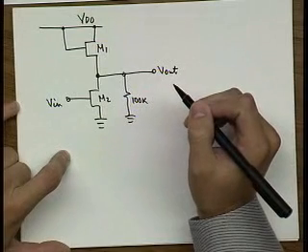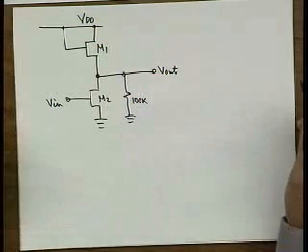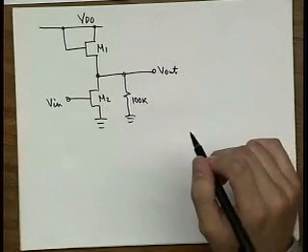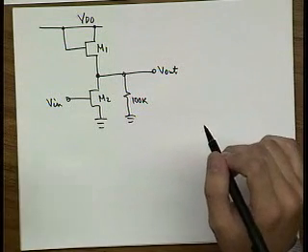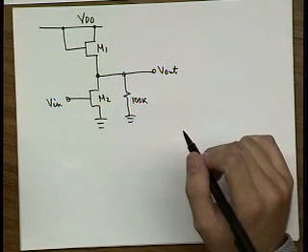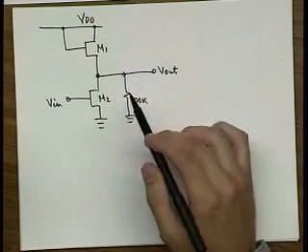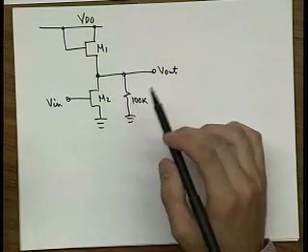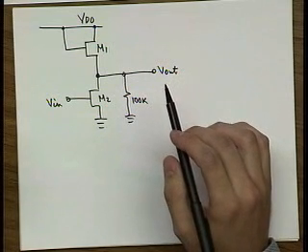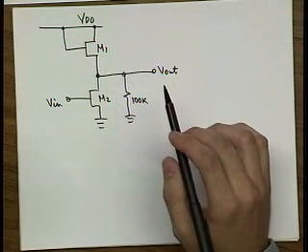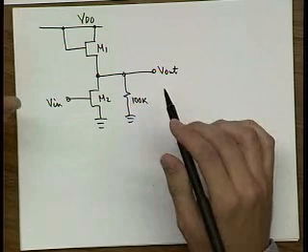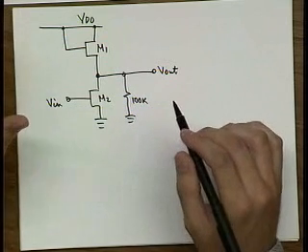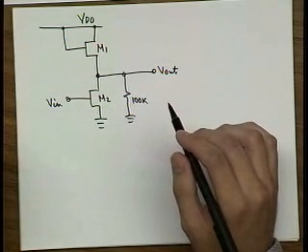And then the question was to find the VOL, VOH, VM parameters. And this problem was further simplified by the assumption that all these transistors are basically long channel devices, so you just ignore short channel effects and, instead of velocity saturation, you do classical saturation. So in that regard, this problem was really a simplified version of what you could have gotten in your homework.